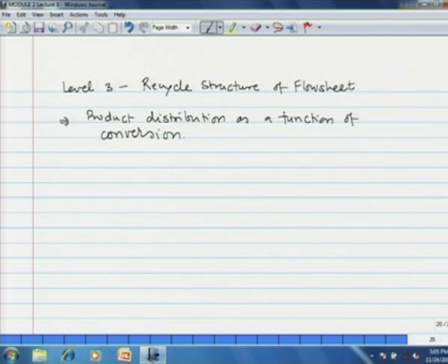Especially for gaseous reactants, we need a compressor, which is an expensive piece of equipment in terms of both capital and operating cost. As far as liquid recycle is concerned, we may need only a pump, which is not at all an expensive component. However, separation of the liquid reactants from the other products could be an energy intensive operation. Now, this usually takes place through distillation columns or distillation train.